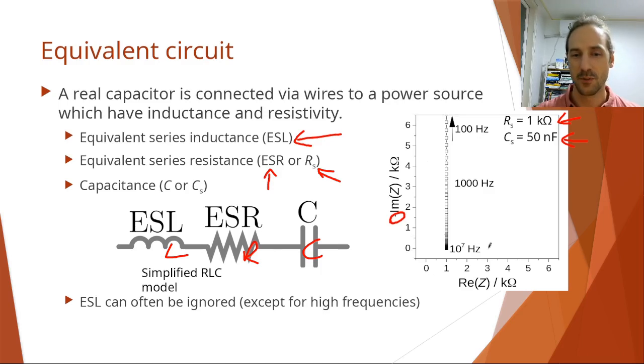And we usually start the measurements at high frequencies. At high frequency, the current is much higher. We can remember that in the high frequency case, the voltage on the two sides of the capacitor changes faster, so the current will be higher, and the higher current means lower capacitive reactance. So high frequency means we will get these points very close to zero.